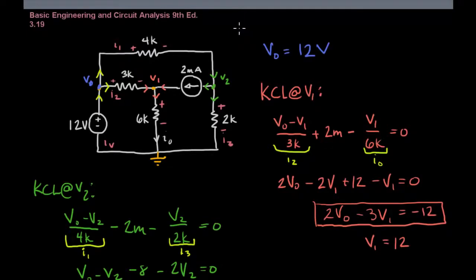So the KCL equation here is IV minus I1 minus I2 is equal to 0. Hence, the current in the branch with the battery is equal to I1 plus I2. Okay, and so that way we're able to solve for all of our branch currents.